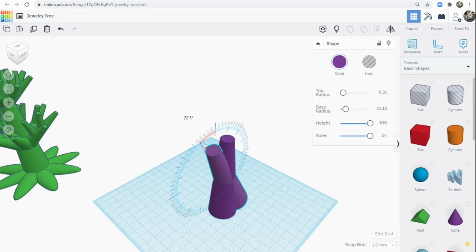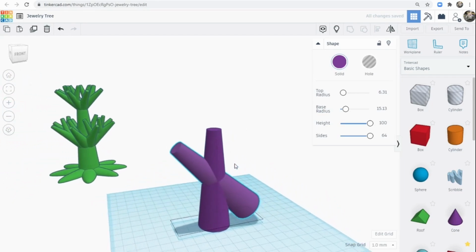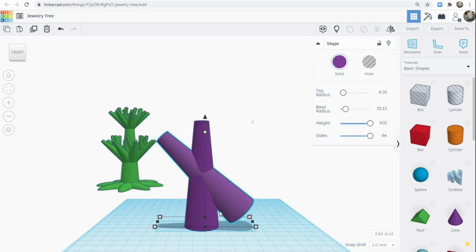So I'm going to tilt my first branch out 45 degrees. The length of our cone is at 45 degrees, and the side is a little bit steeper since it tapers in. And that means that we should be able to print it without supports because the angle goes up so steeply, it'll be each layer overlapping. We'll take a look closer at that in our slicing video.